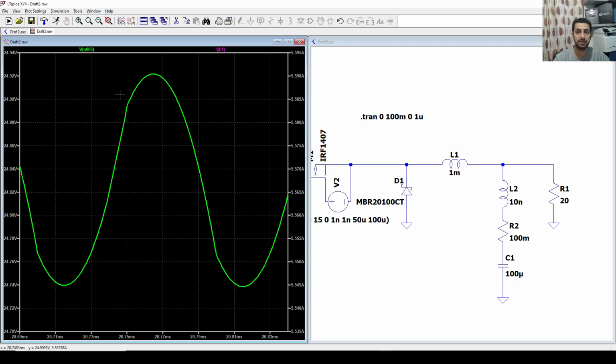Now it seems it disappeared. Okay, so that's why this one is okay, and that's why we want the leads to be short. This is one of the considerations, and also it's very close to the other components, with no long PCB tracks going from one component to another, just to reduce the inductance component and also the spikes that we have seen, because that will also affect the EMI generation, and it might fail your product.